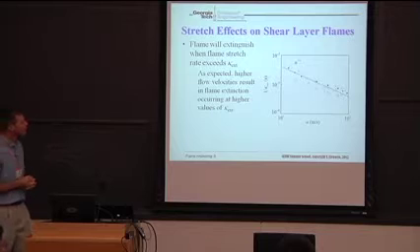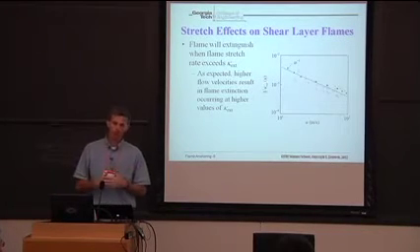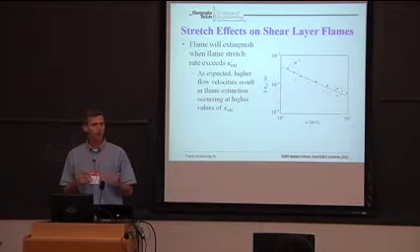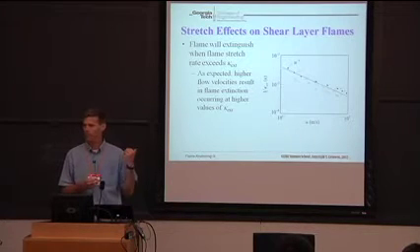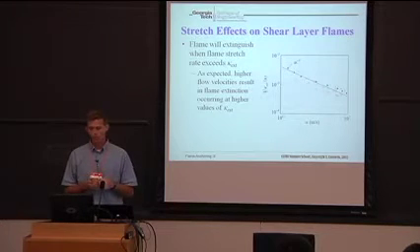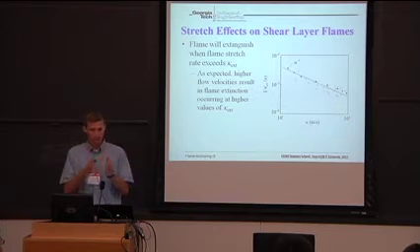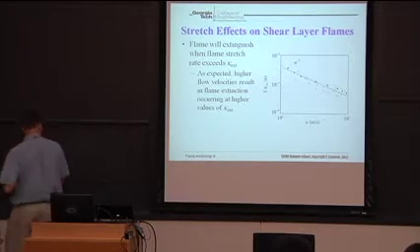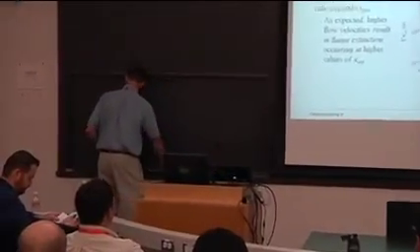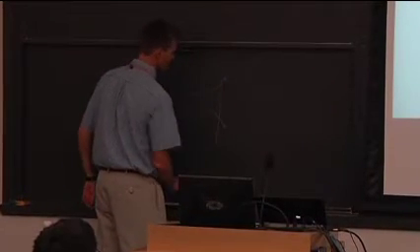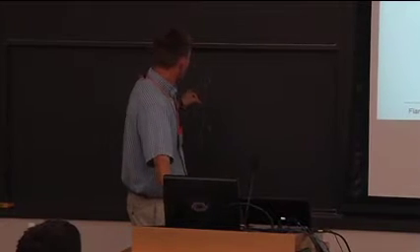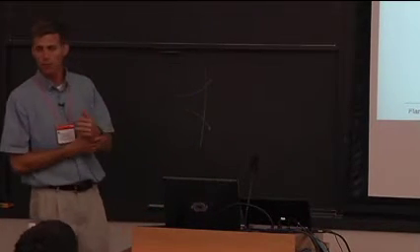We'll figure it out. If you take a laminar flame in a uniform flow, it's got a flame temperature. It has a burning velocity. As soon as you curve a flame, I talked about this before, you change the burning velocity. As soon as you make the approach flow velocity non-homogeneous, as with stagnation flames, so this is a flame, and my flow velocity goes like this, that's going to change the flame speed. It's going to change the local flame temperature. What happens is what I referred to before as the Markstein number. The Markstein number is the sensitivity of the flame to curvature or flow-induced flame stretch.